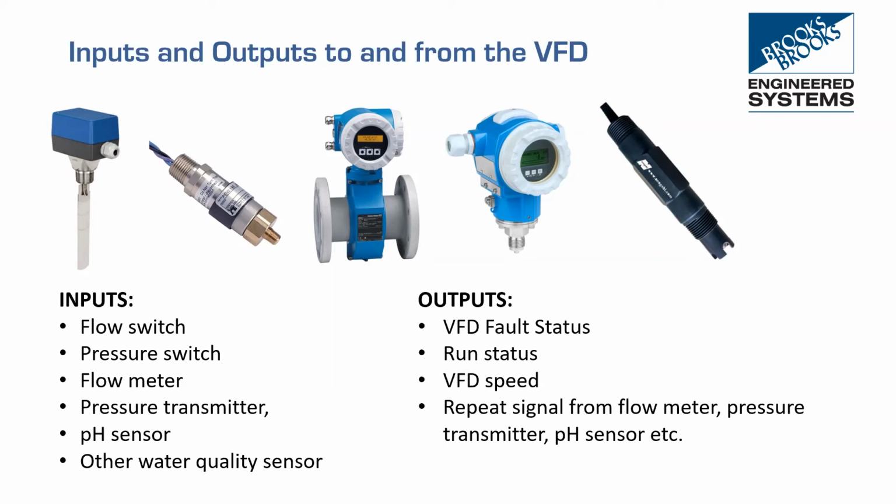If it's a standalone application and there's no SCADA system or multiple variables to control, then yes, a VFD can easily be programmed to maintain one sensor, for instance, a discharge pressure sensor at a certain set point. There are a lot of pre-canned software applications for that, and no PLC is needed. If we're trying to integrate this VFD into a larger control system where maybe we want to satisfy a few different pH sensors with the same load, that's where we would typically need a PLC to help integrate the VFD into the process.